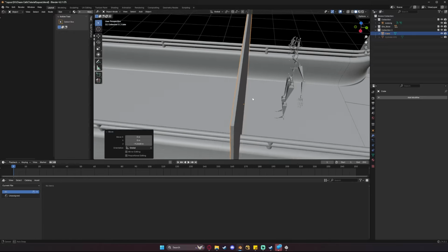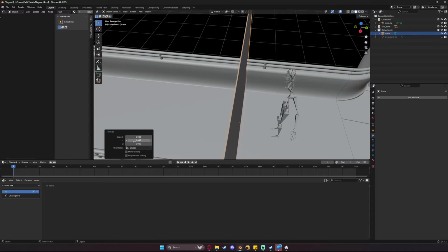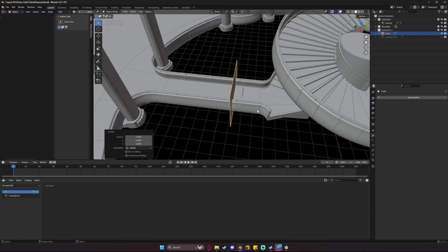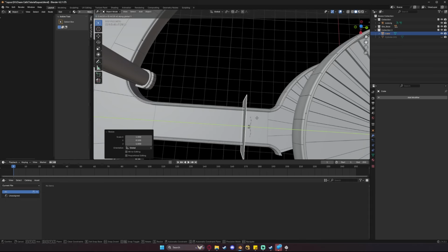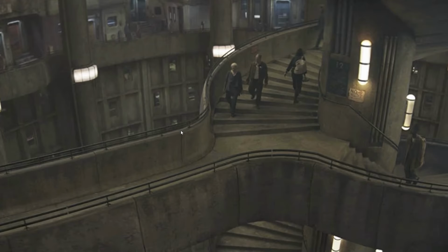Looking at it here, I feel like it could go even smaller, so scale it down just on the Y, 0.5, so make it half of whatever thickness we made it there, and we should be good. And that reminds me that the ground isn't actually being cut into in this shot. What is happening is the sides are being cut, but the top layer where people are walking is still flat. So when we actually cut this, we're going to want to exclude the top floor layer here and only cut in the sides.